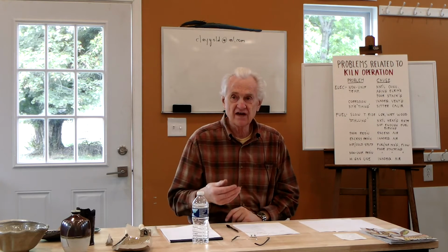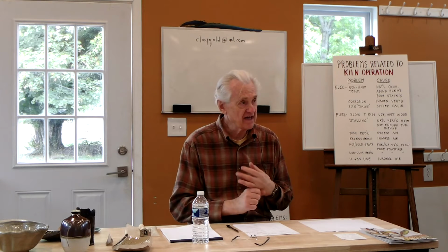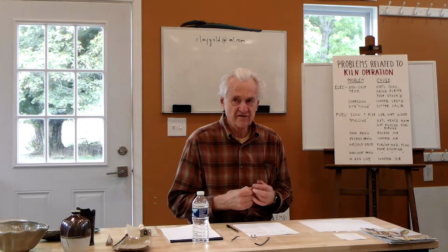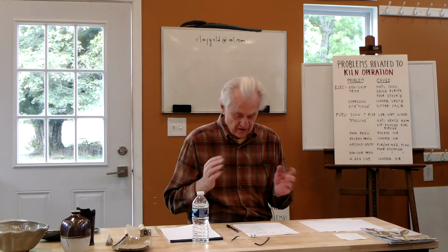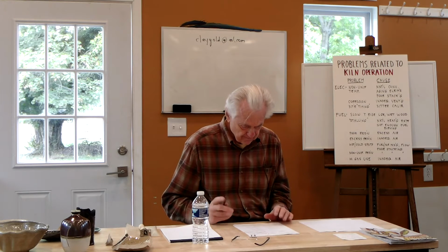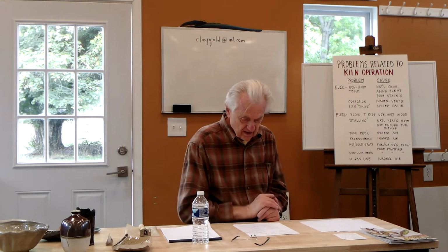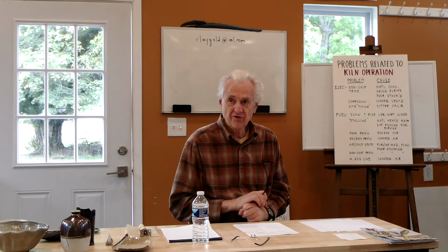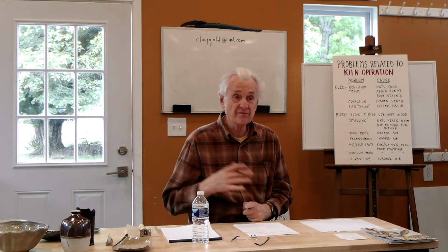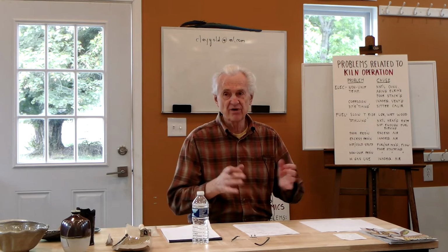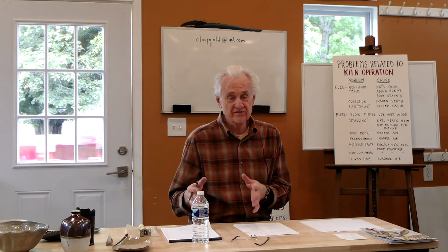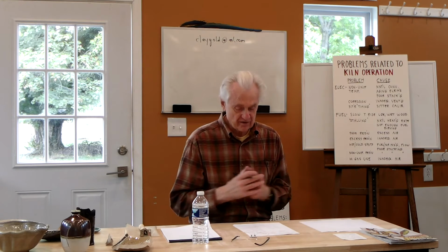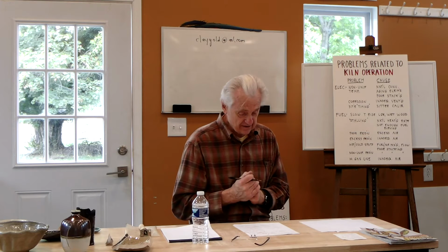The way to overcome that is you have to put in more. You have to burn more fuel. You have to overcome that heat loss. So you have to turn up the gas. You have to increase the stoking rate or change the size of the wood or the amount of wood. Effectively, you have to burn more fuel to overcome that. It's a little easier with gas because you just turn up the gas. But with wood, you have all these other factors: the size of the wood, the type of the wood. Even for instance, softwood like pine burns faster and hotter than hardwood like oak. So even the type of the wood can affect how quickly you're going to get the heat from that amount of wood. So it's a little more complicated with a wood-fired kiln.